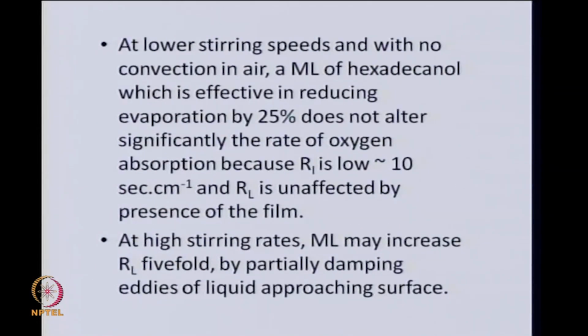At lower stirring speeds and with no convection in air, a monolayer of hexadecanol can retard the evaporation by 25%, whereas there is not much reduction in the rate of oxygen transfer. This is because Ri, the interfacial resistance, is now quite low, about 10 seconds per centimeter, and RL is unaffected by the presence of the film.